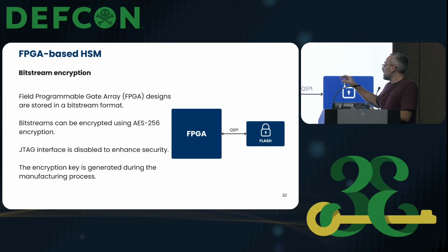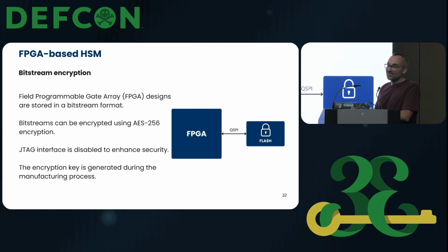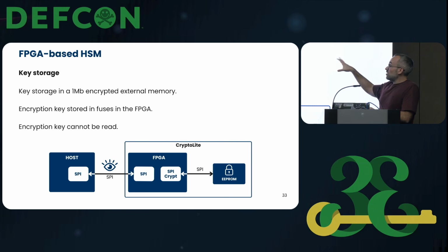However, regarding the handicap that they need an external memory to store the design, AMD, for example, allows us to encrypt the design with AES-256. The good side is that the key is stored within the FPGA using fuses, so it cannot be read externally. Also, if I disable the JTAG interface to prevent anyone from reprogramming that FPGA, it will increase the security. And the encryption key used for the flash memory that stores the design is generated and fused in the manufacturing process of the FPGA.